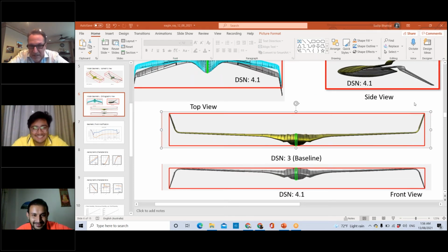Okay, yeah. So if I look at this, my instinct would be to take the very center bit that's high and push it down low. That's going to fill in the divot in the lower surface. It's going to get rid of the hump on the top. So things are going to naturally smooth out quite a bit if I shear the airfoils so that they make a smooth shape on the upper surface. I think it's good. And usually you'll find that has a very small effect on the aero.